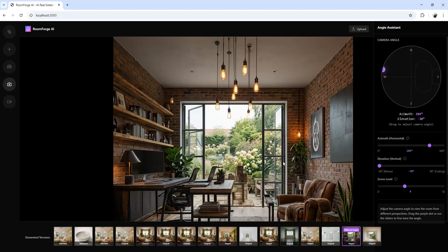So this angle picker works like a globe. The floor view, minus 30, is like an equator. The largest radius azimuth rotation traces the largest circle. Eye level view is 0, mid latitude, medium radius, smaller circular path. And zenith is 90 degrees, like a north or south pole. Radius approaches 0. Azimuth rotation barely moves the indicator.